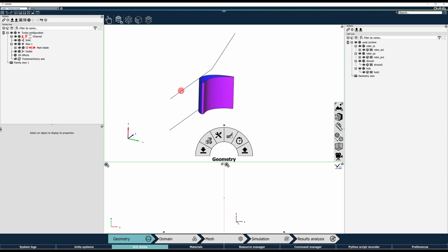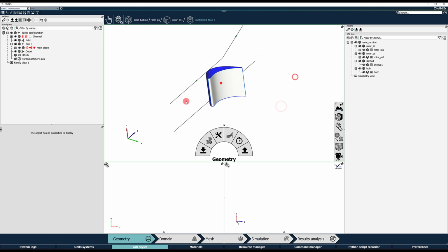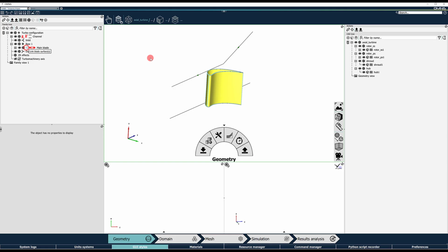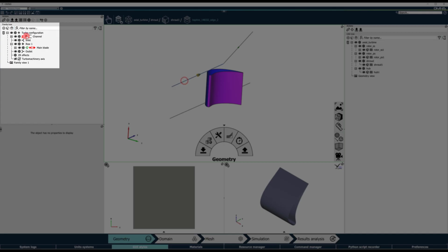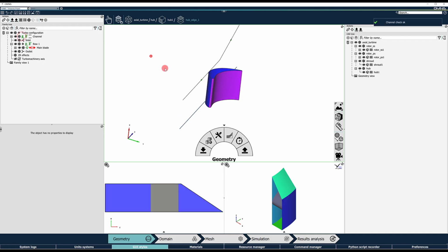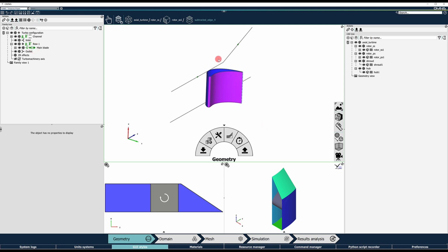Note that only surfaces related to the suction and pressure sides, together with the surfaces related to a round or sharp leading and trailing edge, should be linked to the blade. By clicking the red icon dedicated to the concerned entity, the selected surfaces and curves will be linked and the icon will turn green. The linked entities will be shown in the meridional and 3D turbo views.